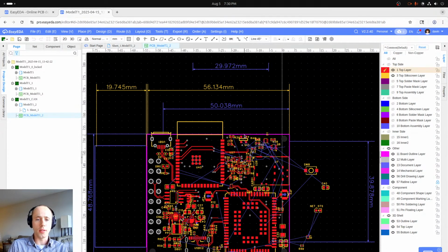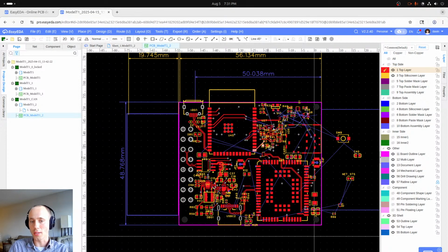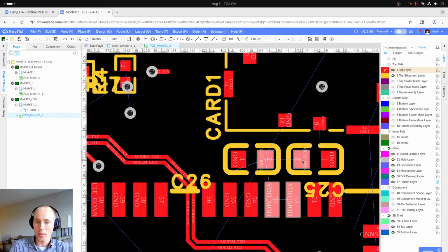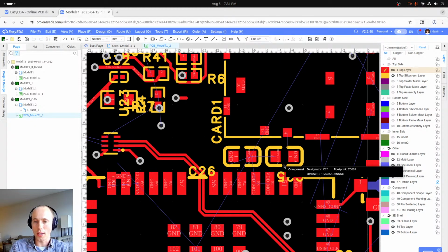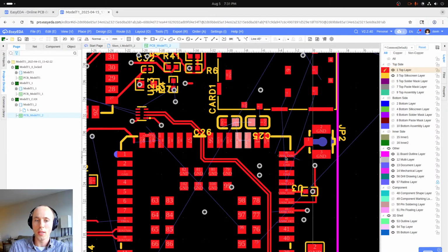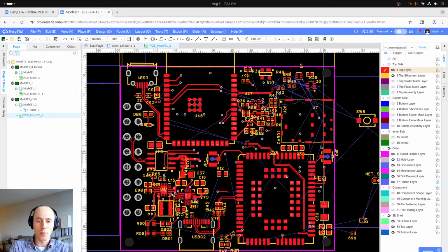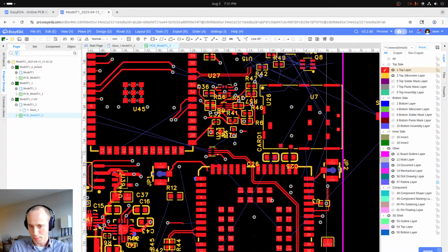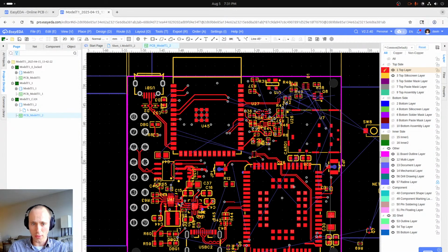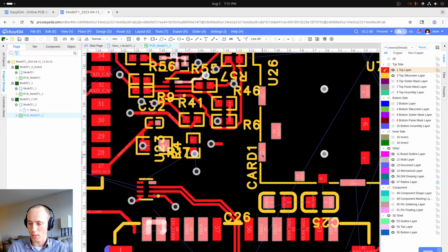So what are we going to do today? Pretty much what we discovered last time is that a lot of these components are simply not placed in the correct spot. For instance, these capacitors are decoupling caps that are supposed to be tied to the pins of this rail. We found a lot of stuff like that, where components wanted to be close to the pins but never landed there. Several components really exhibited this, and we had to move the SIM card slot up in order to accommodate these capacitors.